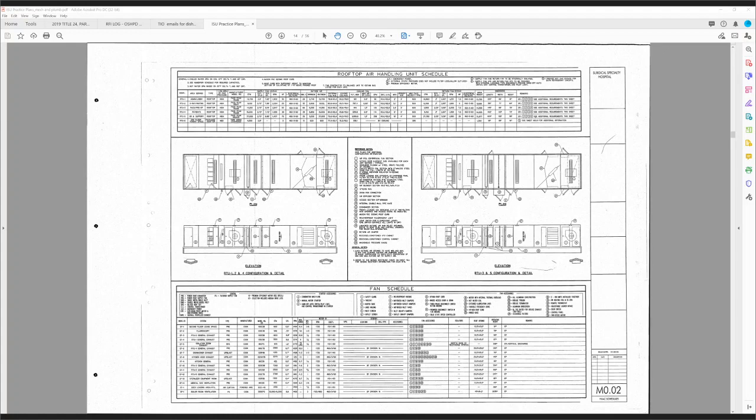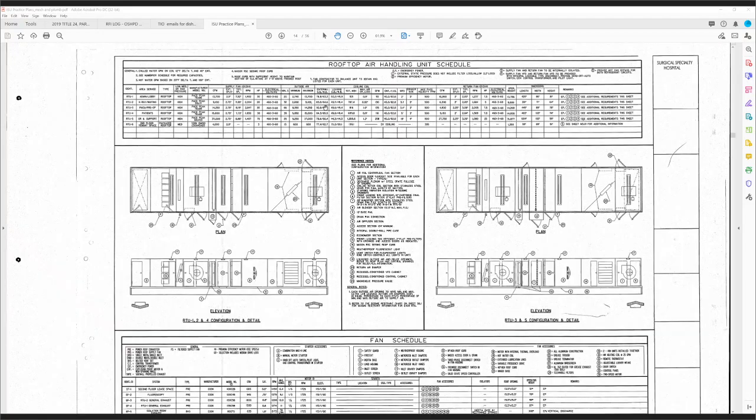So Caesar, could you zoom in on this a little bit? Brian, I did also look at that 120 volt circuit that went to the lights, and I contemplated that too. And then that's when I went back to the equipment schedule to study that. But you're right, it doesn't say necessarily that it's derived from the 480 circuit. But if you zoom in on the notes in the middle and the right hand, yeah, that would help. Let's see.